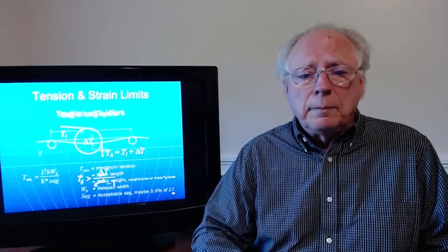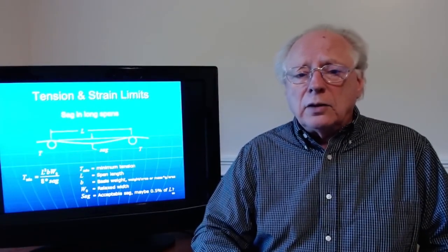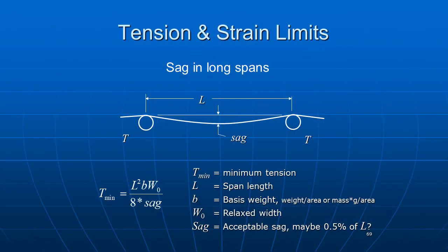You're going to slide. Now, sag in long spans. If you have a very heavy web or very long spans, this could be an issue, but it does dictate a minimum tension. How much sag is acceptable? My rule of thumb is 0.5% of the span length. And that is a rule of thumb. There's no science to that one.